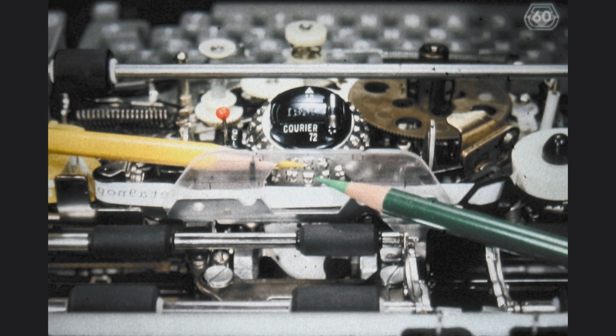Old-style support screws for the detent actuating lever came equipped with an eccentric stud for mounting the lever. The objectives of the adjustments remain the same: a maximum of 0.25 mm clearance between the cam follower and the detent actuator when at the low point of the detent cam, and 0.89 mm skirt clearance when on the high part of the detent cam.